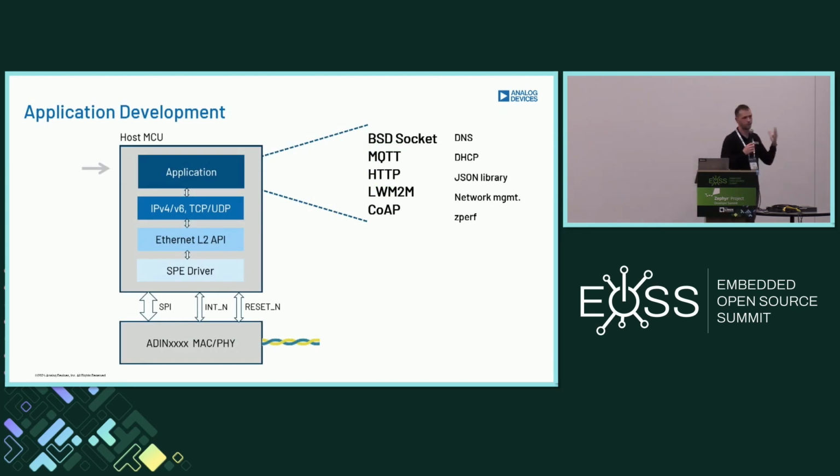For those who have worked with Zephyr's networking stack, be it with Wi-Fi or 802.15.4, whatever the physical layer, the same APIs and libraries can be deployed with single pair Ethernet, so nothing changes here. And I think this is one of the beauties of Zephyr, the ability to reuse code across different physical layers without the need for much porting.